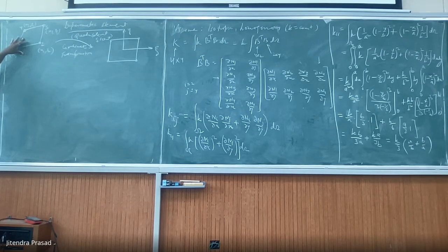The problem is it varies linearly, right? So its order is limited. It is planar basically: alpha plus beta x plus gamma y. If you use a quadrilateral, at least you will have a higher order, one order higher. This is better. So that's why you will not change it. It's better to use this one.